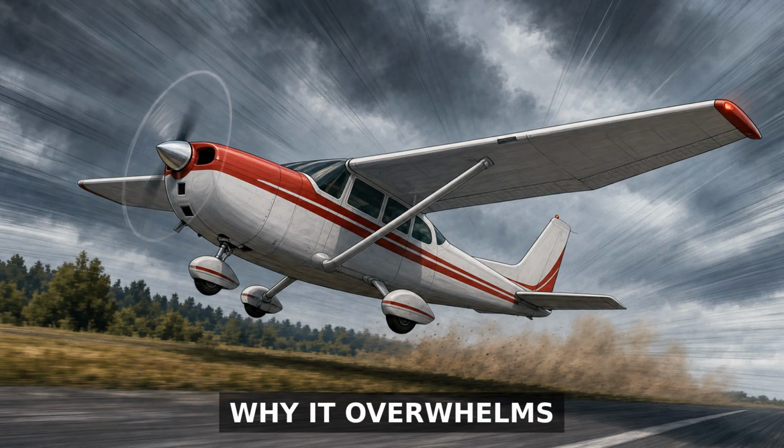The danger is that the tailwind phase takes back more than the headwind gave you. Your airspeed drops below approach speed. Drag rises, and the sink rate can exceed your climb capability. Near the ground, there may be no room to recover.